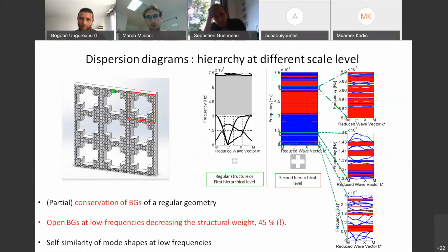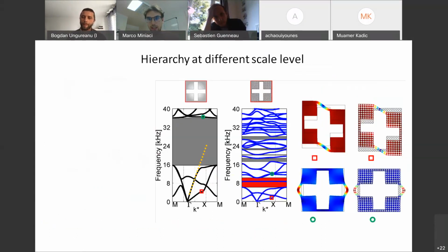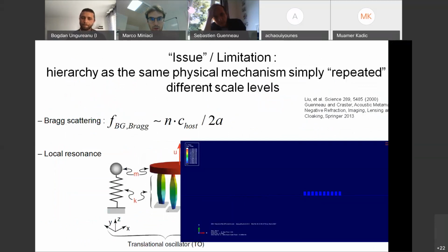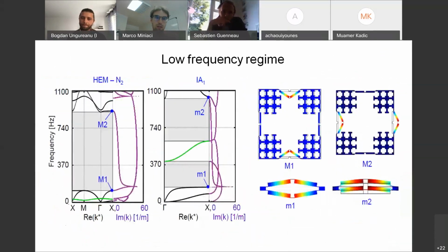So standard Bloch-Floquet without adding any dependence from viscosity, frequency, or time. Instead, in the next session, the calculations were made assuming that the stiffness and mass matrices were frequency dependent, and so there was an imaginary component of the wave number that could be calculated. Okay, thank you.